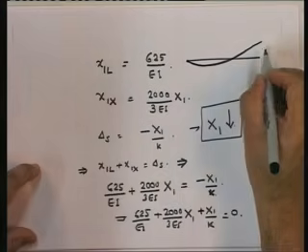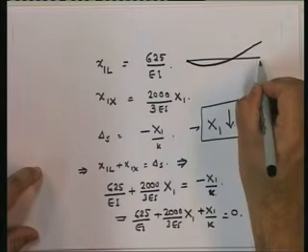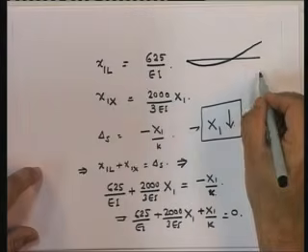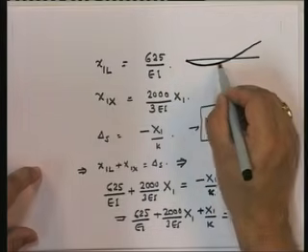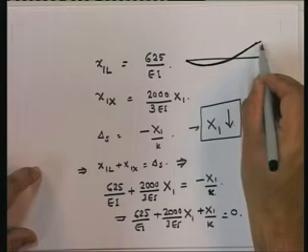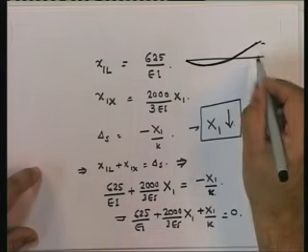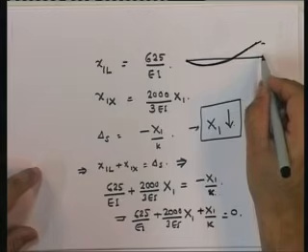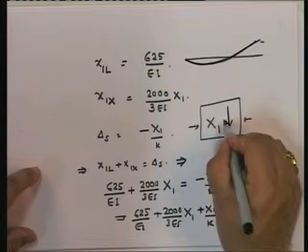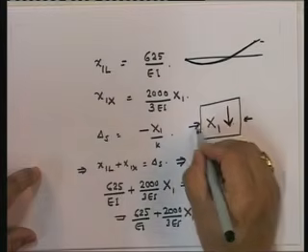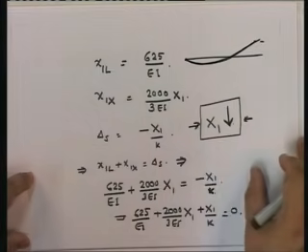So in reality, due to the loading, you're going to have a compression in the spring, but due to the deflection, you're going to have an extension in the spring, and therefore the compression in the spring is negated a little by the extension, and therefore the value of x1 goes down due to the foundation flexibility.